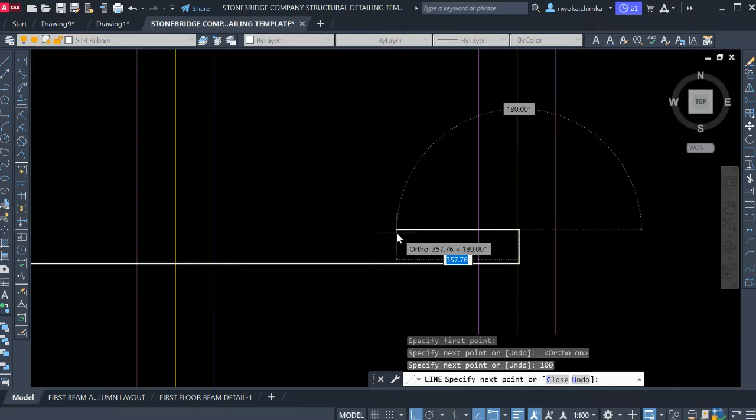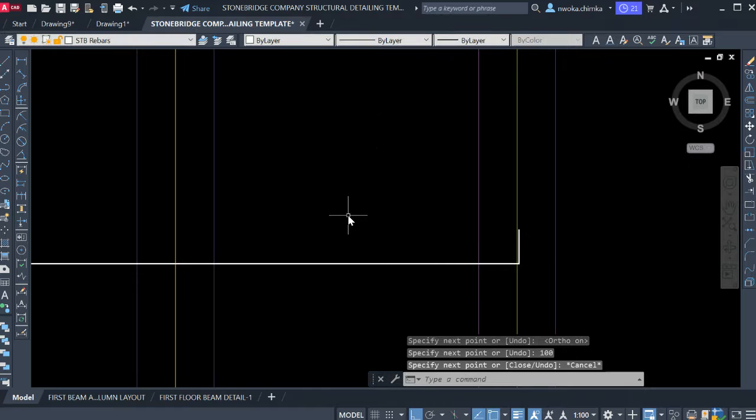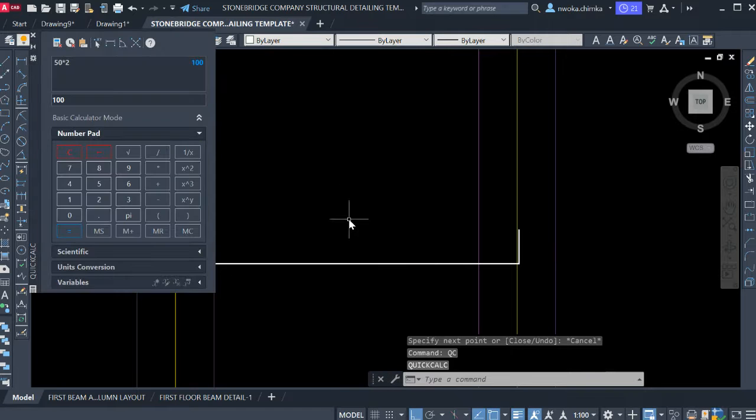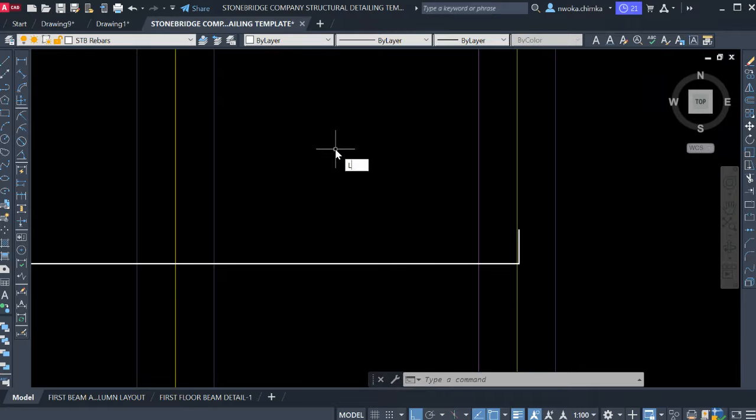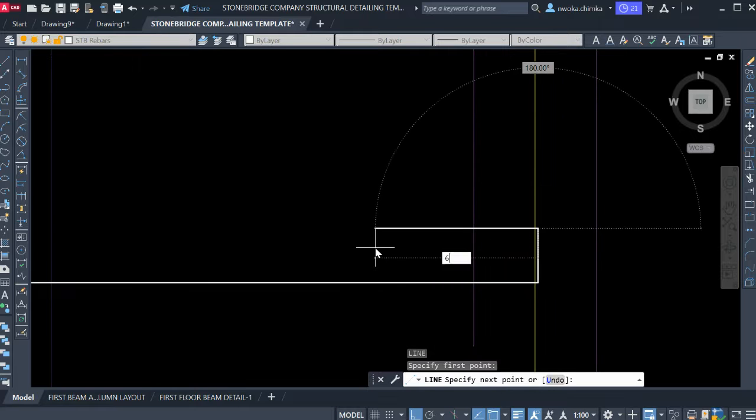is 12 millimeter. So what I'll do right now, to put my anchor here, I'll have to use the rule from the British Code of Practice, or for a standard of slab detailing, I'll just say 50 multiplied by the diameter of bar, which is 12 I'm using. That gives me my lap length of 600 millimeter. So I'll just go and click on line, click on this point, and then go over here and type 600,